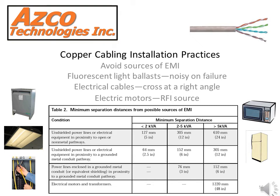Avoid sources of EMI, electromagnetic interference: fluorescent light ballasts, electrical cables. When you do come across electrical cables, only cross them at a right angle. Also avoid electrical motors and RFI sources. As you can see here, we've noticed electrical panels, light fixtures, transformers, fridges, microwaves, anything that can create a signal to interfere with the actual Cat5e or Cat6 cable and degrade its performance.